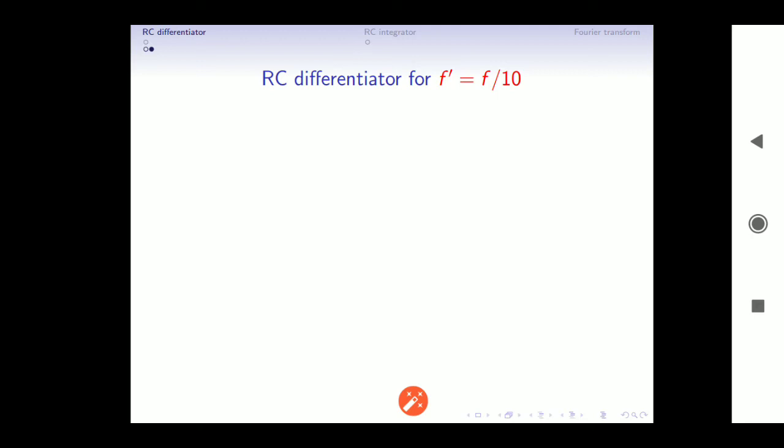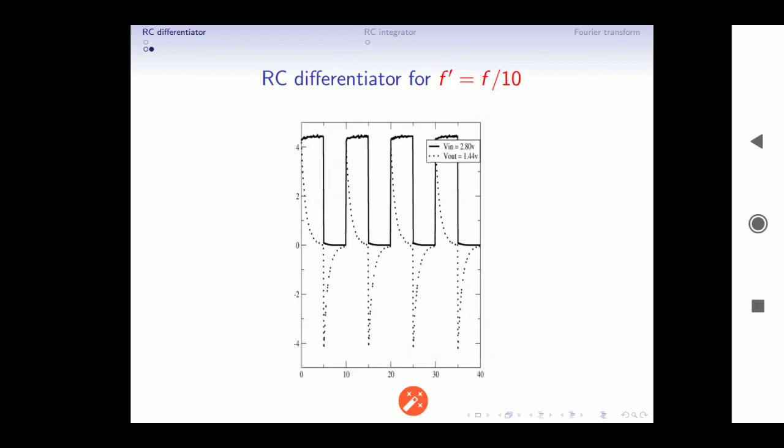We know that if you use a sine wave, the differentiation of a sine wave is a cosine wave, and similarly the differentiation of a cosine wave is a sine wave. So if you provide a sine wave, it's not difficult to identify what the output would be. Instead of a sine wave, if you provide a square wave, what is the output? That one actually has to think about. For the applied frequency, which is 1/10 of the design frequency, the output looks something like this.